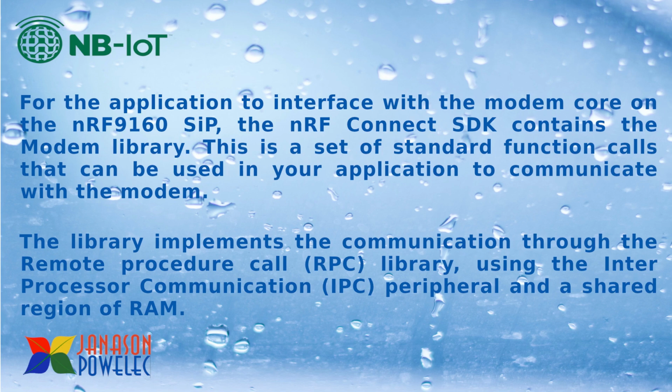For the application to interface with the modem core on the NRF 9160 SIP, the NRF Connect SDK contains the modem library. This is a set of standard function calls that can be used in your application to communicate with the modem. The library implements the communication through the remote procedure call RPC library using the inter-processor communication peripheral and a shared region of RAM.